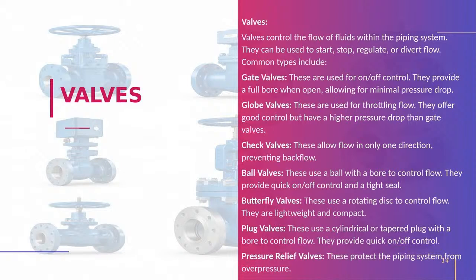Based on the services, what type of valve we have to choose. If it is a semi-solid service, what type of NRV we have to choose. Same for gate valve and globe valve and all. Where we have to choose a flanged valve, where we have to go for a welded valve, where we have to go for a screwed valve. Everything we will see in the detailed schedule when we discuss the piping components and valve modules.